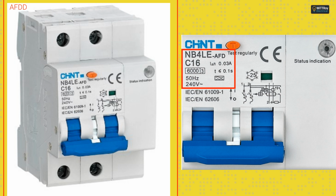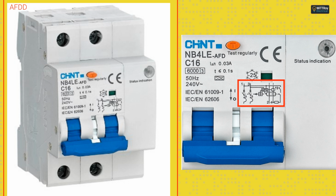I can see I delta N 0.03A type A symbol and a test button. That means it also has 30 milliamp type A RCD protection. From the diagram, we can see the MCB function, the RCD function, and the AFD function together. So this device is an AFDD with MCB and RCD protection built in. It provides arc fault, earth leakage, overload, and short circuit protection.